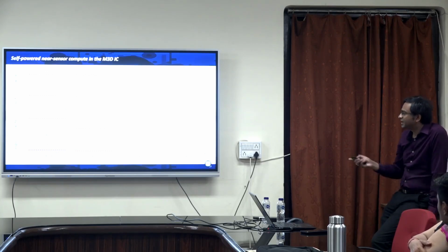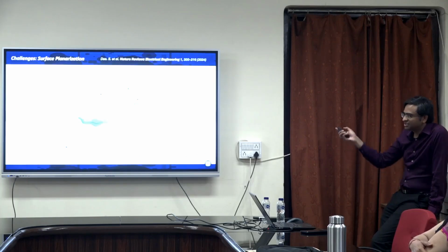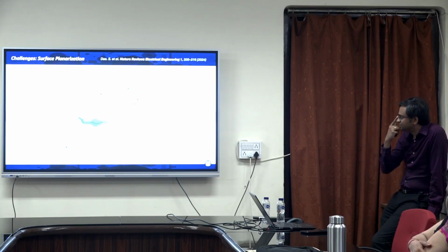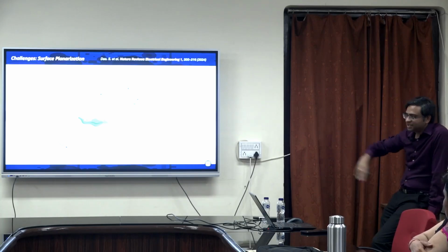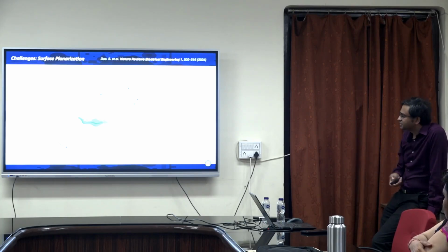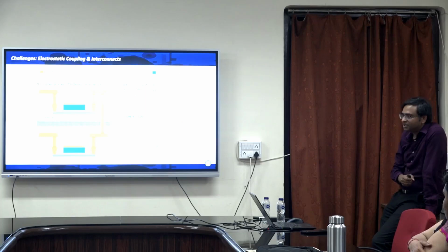Okay. So we were able to do this. And these are the remaining challenges that we wanted to solve. This is something we discussed in this review paper. As I told you, if you're interested in 3D, you can read this very detailed review paper. The chemical mechanical polishing has yet to come. We cannot do it now because our chips are too small. You will also need electrostatic decoupling, and your interconnect has to be properly designed.